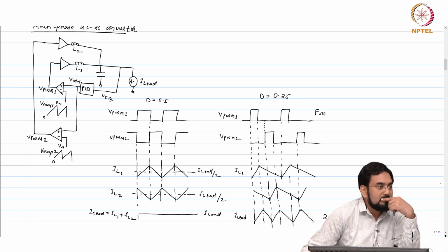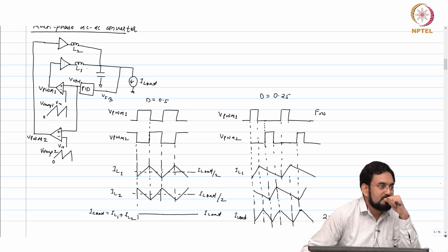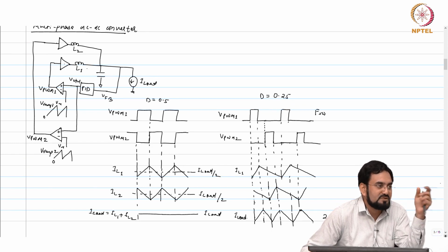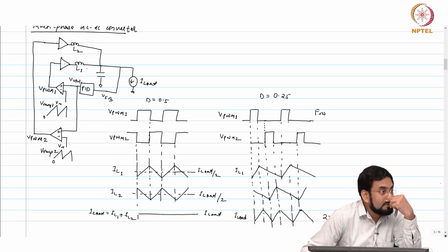So what you do, you equally split the power FET. So instead of sizing the same, let us say you require 100 milliohm for 1 amp, and now it will be catering only 500 milliamps, so split into half, so that your total area of power FET remains same. But what about the inductor? I cannot reduce the size of the inductor.